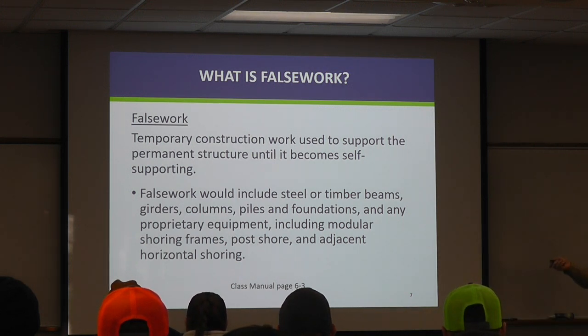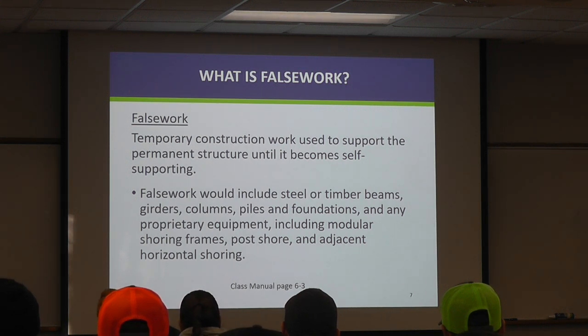So it's temporary construction work used to support the permanent structure until it becomes self-supporting. So falsework would include steel or timber beams, girders, columns, proprietary equipment, shoring frames, and different things like that.